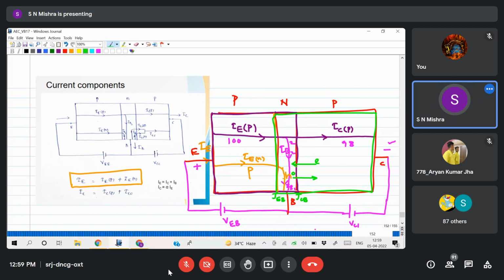So electron is moving from collector to base. So what is the direction of current? Base to collector. So you see here, this one is your ICO due to electron. ICO, I have written here ICO due to electron. Similarly, hole is moving from base to collector, means the direction is base to collector. So the upper one is ICO, P is written. You see here ICOP, ICON.